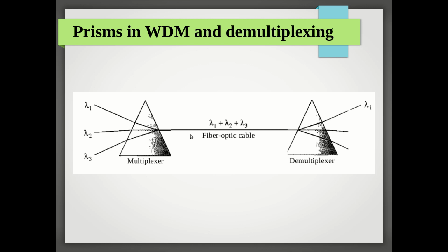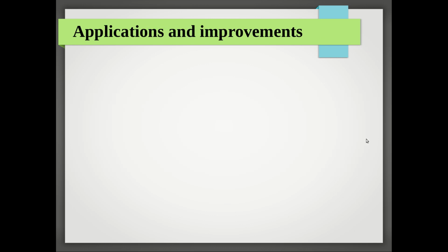In that way we set up the prism and the angle of incidence, and the signal travels as a single unit over the fiber optic cable, and on the way you can place optical amplifiers. After boosting and traveling a very long distance it reaches the receiver, where the demultiplexer module again has a prism, and based on different frequency it bends the signal like this, and correctly delivers it to the receiver. This is just a diagrammatic view of what we explained.